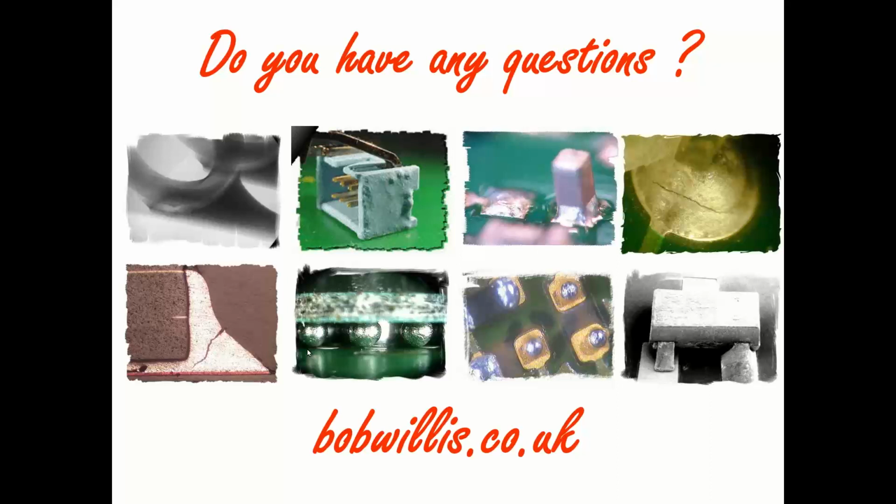If the coating expands at a far faster rate than anything else on the board, then you will create cracks in solder joints. So that's why with BGA, as an example, or QFNs, there have been examples of where joints have broken with conformal coating, but only after environmental testing. So that's sort of answering your question and also coming on with another suggestion.